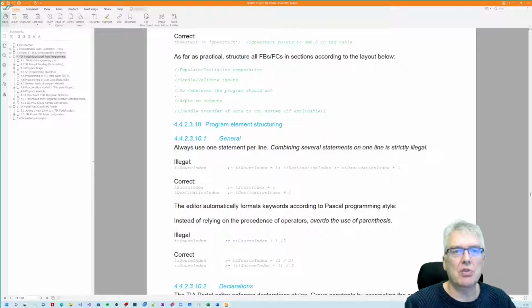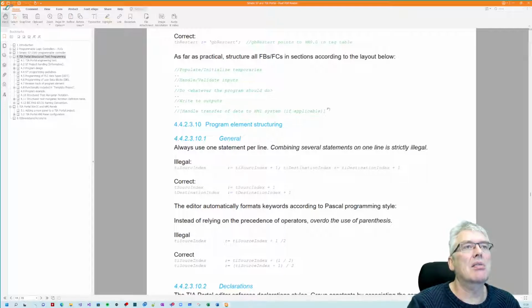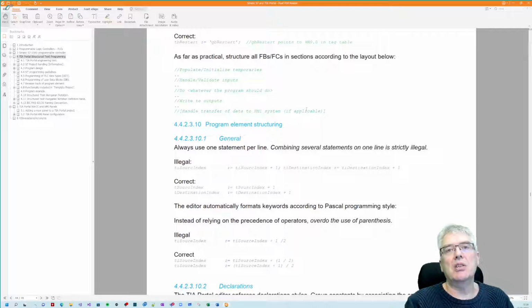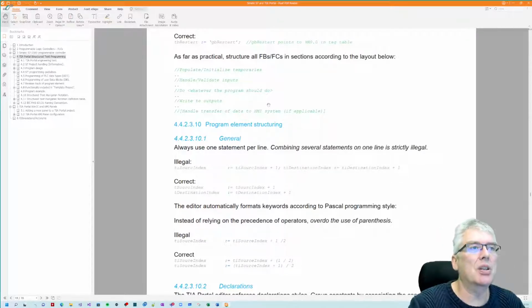Write to the results, to the outputs. These are function blocks or functions. And then we don't have to look there. If you have an HMI system that needs variables, it should have its own variable. Do that at the end, because then you have produced the results you need, so you don't transmit some intermediate results to your HMI system or something, because your program is done. And now you can say, okay, what I have produced here, it's the same as the outputs. What I have produced, write it to the outputs. I finished with my processing. What I am outputting is correct, hopefully.